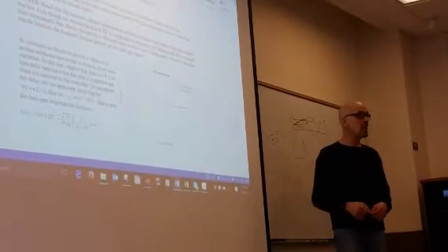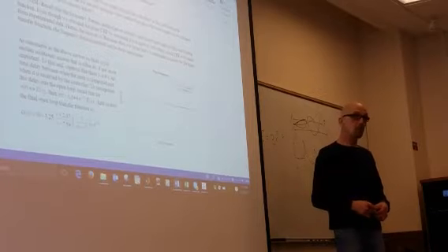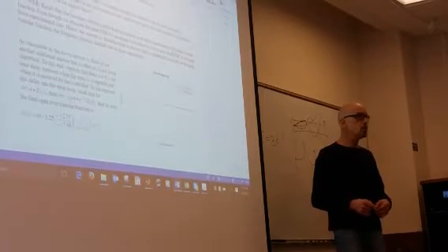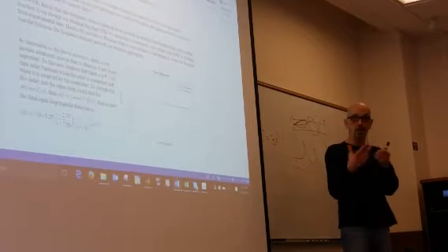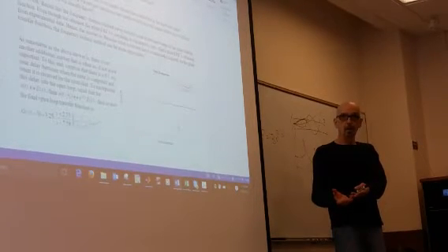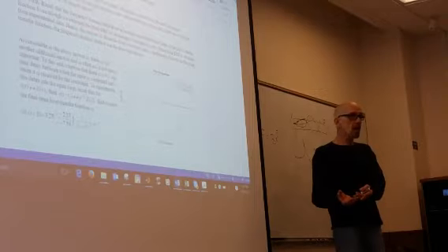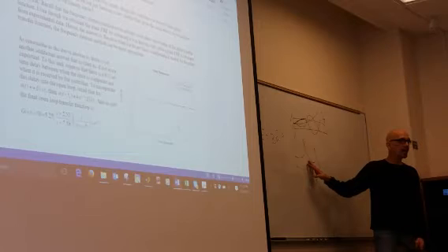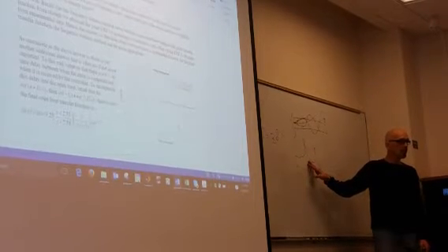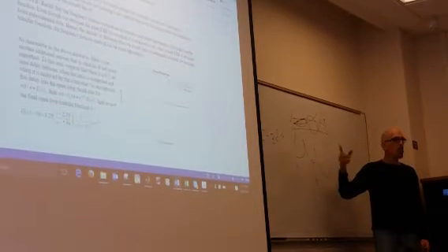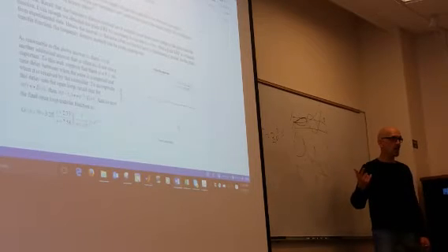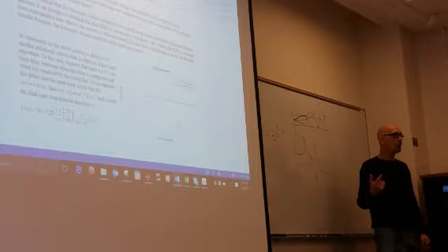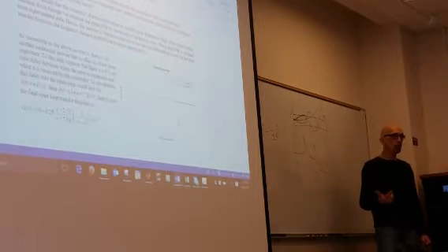So all you have is an FRF. Now you can't do root locus unless you know where the poles of the plant are. You know where your controller poles are going to be. You're going to design your controller. But you don't know where the plant poles are. You have no model for the plant. All you have is this experimentally obtained FRF of the plant. So that's one reason for doing this method. For the test engineer, you don't need to get a model for the plant in order to control the plant.